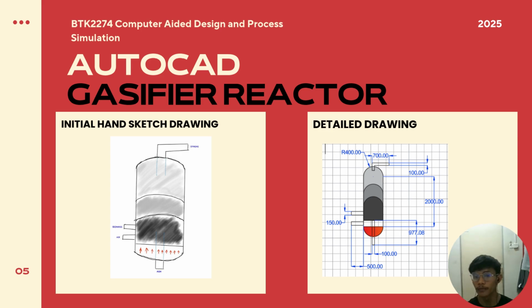The core of the system is the fluidized bed. A gasifying agent is blown upwards through a distributor plate at the bottom of the reactor. At a certain velocity, this gas lifts and suspends the solid bed material and biomass particles, causing them to behave like a boiling fluid. This creates an excellent mixing and uniform temperature distribution throughout the bed.